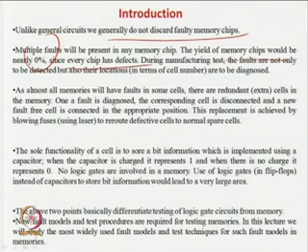So here we have to take a different philosophy. As we discussed right now, more or less 100% of the memory chips will have 1 or 2 defects. So you cannot throw them out. What is the idea? You have to repair them and ship them. So what people do is that they take the memory ICs, and while fabricating, say, 1 GB of memory, they will fabricate something extra. It will not be exactly 1 GB, it will be something more than that.